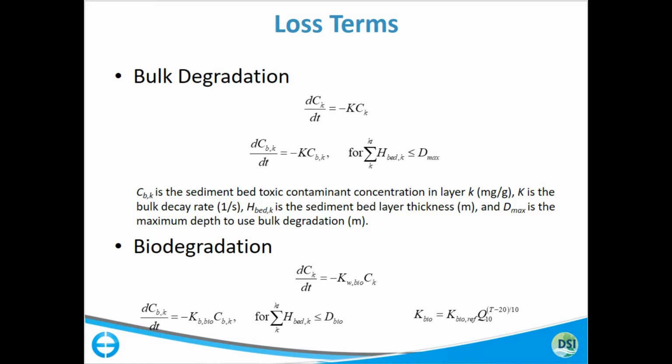Especially if you've got pore water diffusion and particle mixing in there, what's in that super thin active layer? We're literally talking 2 to 3 times your D50 value. So it's really, really small. So we take that active layer component and we add it to the deposited layer. And that becomes the new top layer.